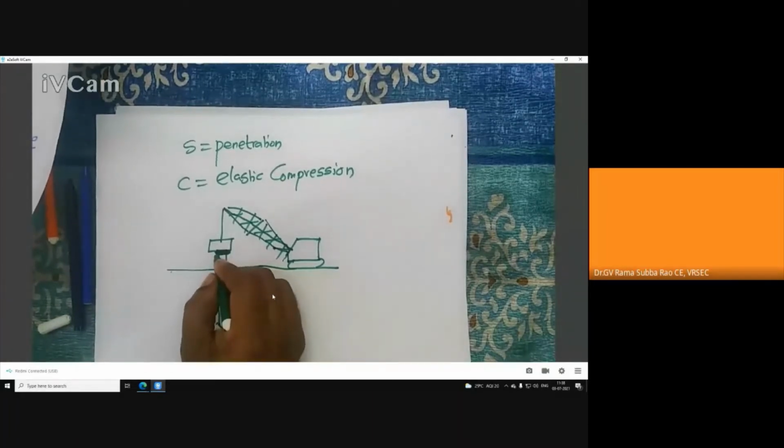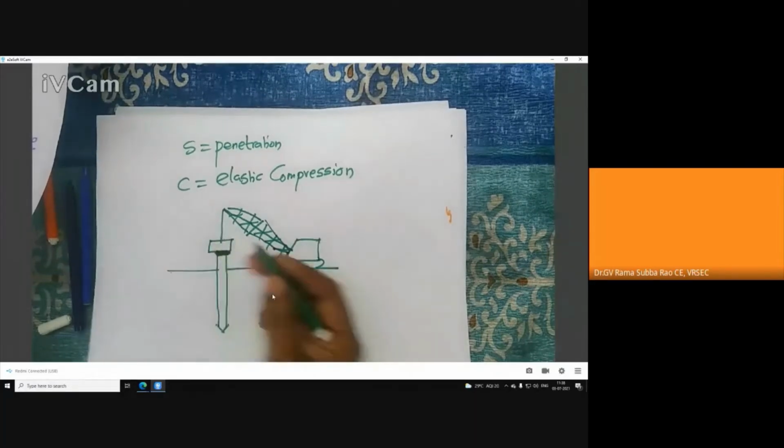So in order to control damage to the pile top during application of the hammer energy, they put some packing. This we call cushion also. Many times we use jute cloth, and we also provide plywood so that we can resist the damage at the top of the pile due to hitting of this hammer. This is a hammer.